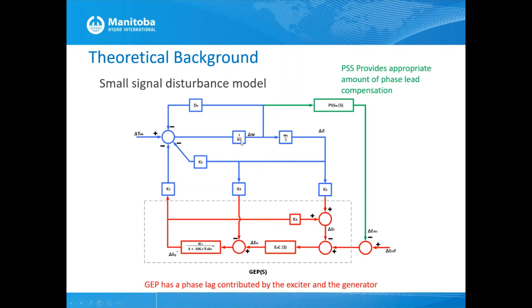The M is 2H, where H is the inertia constant, and if H is large, you are less sensitive to torque changes. In other words, you have more stored energy in the rotor mass if H is large, so you will dissipate more energy before you slow down. For the same amount of power difference, your delta omega is lower if the inertia is large. So inertia has an impact on how fast your frequency changes for the same disturbance.